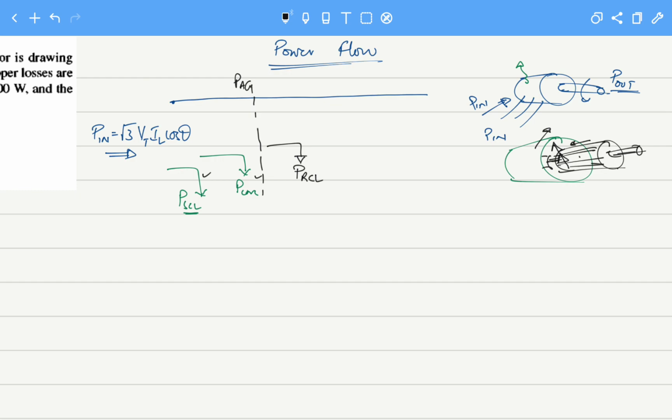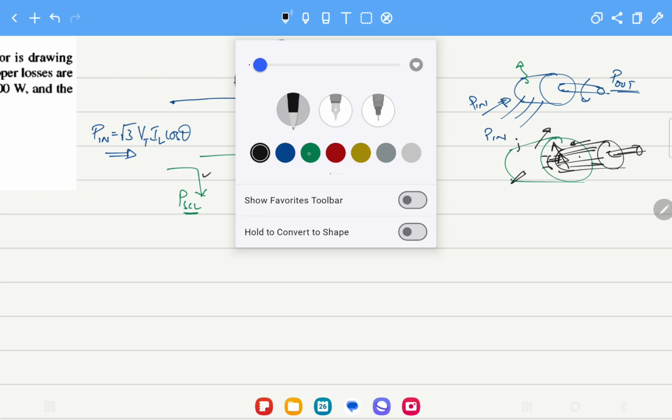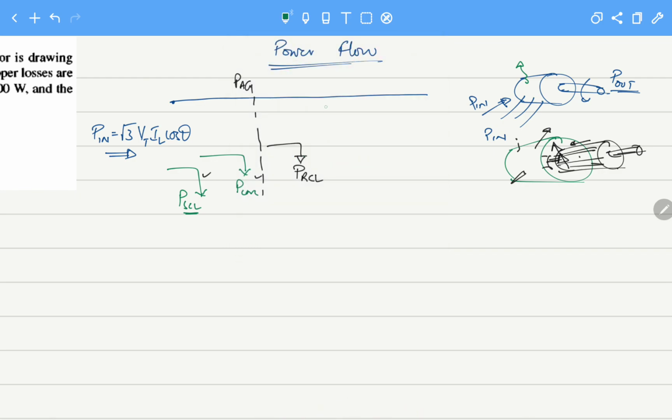So first, the power entered the stator. There were losses in the stator winding. There were also magnetization losses, eddy current losses, hysteresis loss, core losses. And from then the power traveled through the air gap and got induced over the rotor. It is still electrical phenomena through the induction. Power is lost at the rotor. And once the power is lost in the rotor, then we can say that the power is now converted.